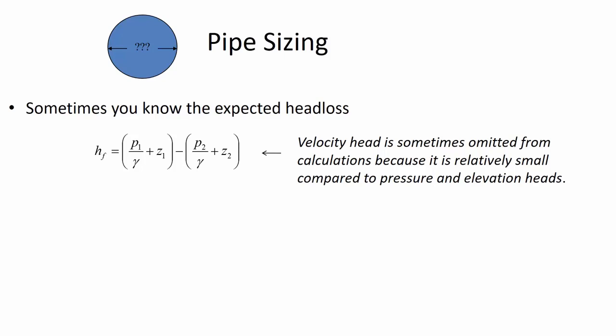This is relevant, but when you have a pipe that's underground, can you have pressure added to the depth underground? Pressure added to the depth? Yeah, like to the water from it being underground at a certain depth. Well, here there's more water pressure in the pipeline than when you go back up above the surface. Also, if you had a hill sloping this way, you're gaining pressure because you're getting further away from there. But there's nothing magical, like the soil pressure on the pipe. That's not going to give any usable pressure.